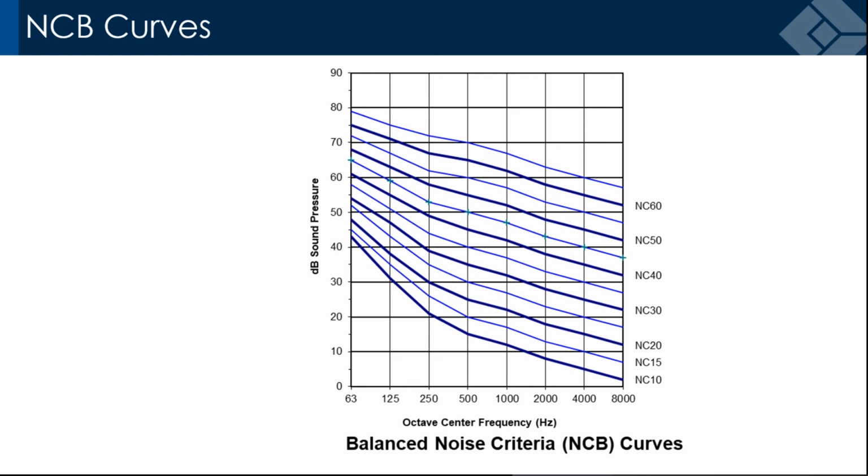It'll tell you a little bit about the character of the sound. So if you see an RC35 with an R after it, that means there's a rumbly sound, so low frequency. And if you see an RC35H, it means it's got a hissy sound. I personally like that method, although I think ASHRAE's TC 2.6 thinks it's more of a figure out my problem thing than a specification of new products thing.